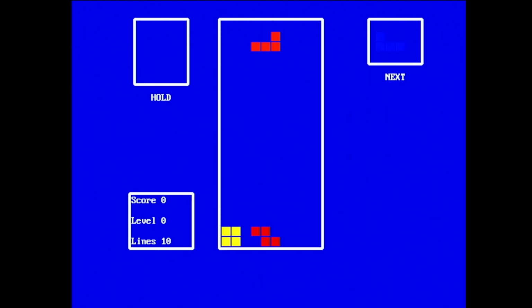Okay, so you can see here, this is better. You can see there's much less interference. Occasionally you do get the odd bit of interference. I think when the bottom line is hit, it sometimes results in some interference. But generally we were trying to make sure that we're only updating the screen during the blanking periods.